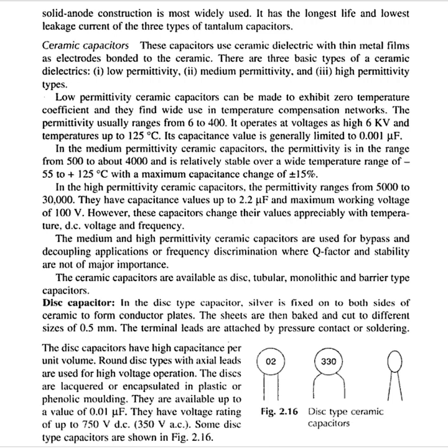In the medium permittivity ceramic capacitor, the permittivity is in the range from 500 to about 4000 and is relatively stable over a wide temperature range of minus 55 to plus 125 degrees Celsius with a maximum capacitance change of plus or minus 15%.